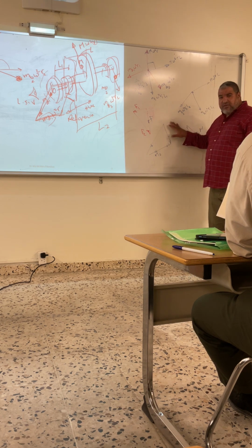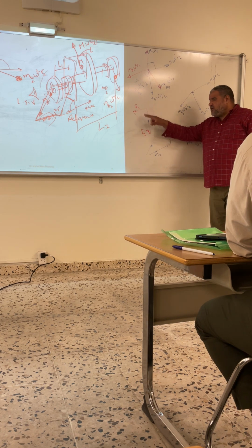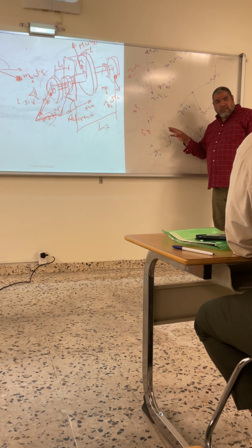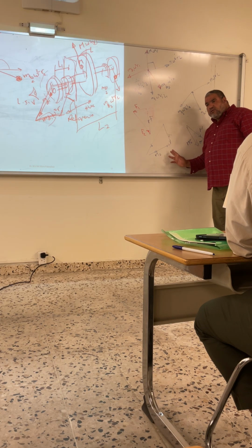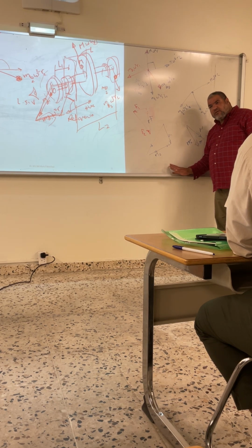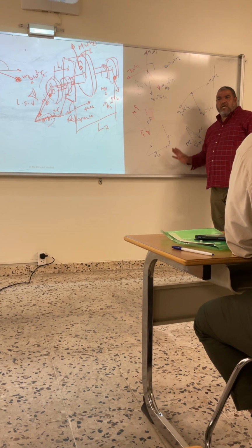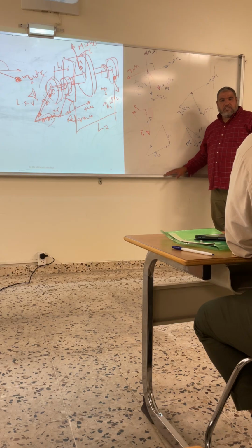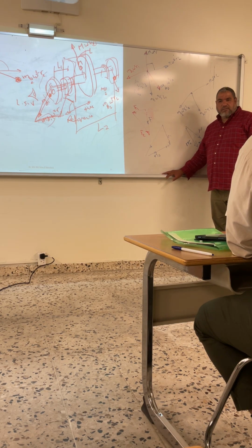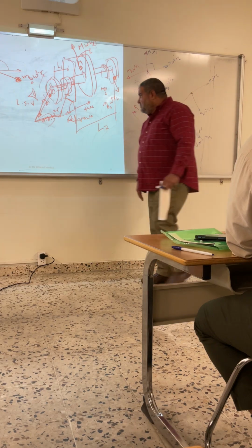You do your business graphically. You start by having the forces, and then you move to the moment diagram. Check your L, the distance. Is it positive? I'm going to represent my M in the same direction as the force. Is it negative? I'm going to represent it in the opposite direction. And you end up having the equilibrium condition. That's it, guys. This is the whole story. Okay, so I'll get back to the slides.